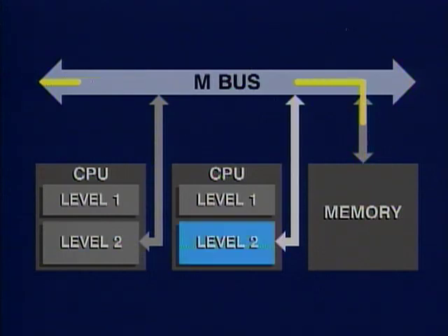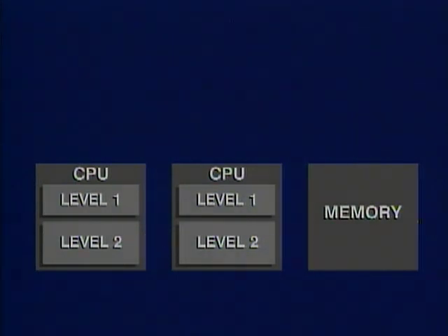Because all Level 2 caches monitor memory space bus transactions, they can continually determine whether cache entries are exclusively in their cache or are shared by 2 or more caches. The Snoopy cache can also determine whether an entry has been modified. The Snoopy cache uses this status information to maintain system-wide cache consistency and to minimize the M-Bus bandwidth. The Snoopy caches use a write-back function for unshared entries and a write-through function for shared entries.